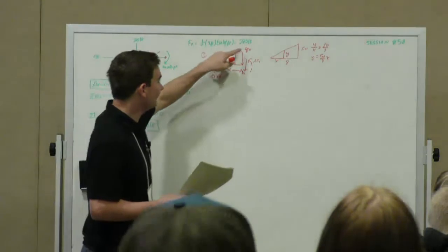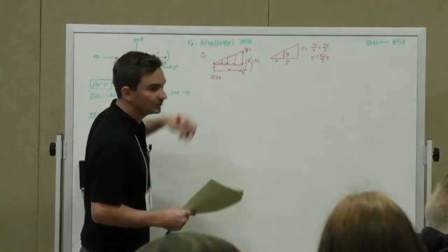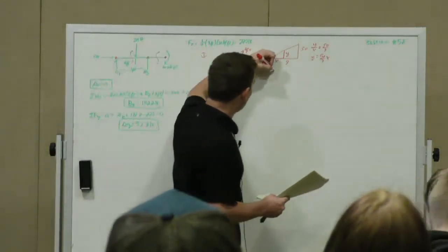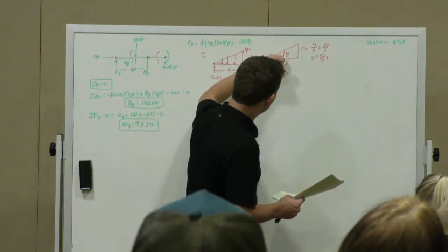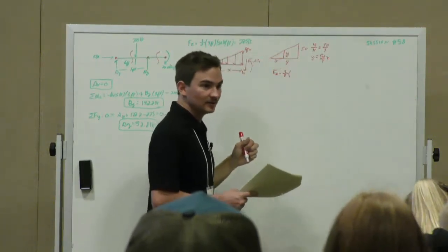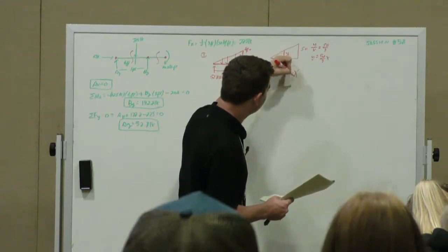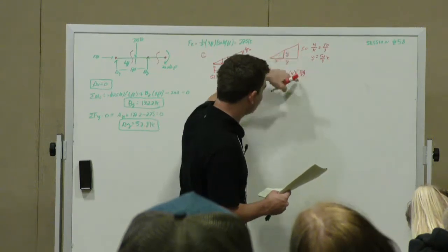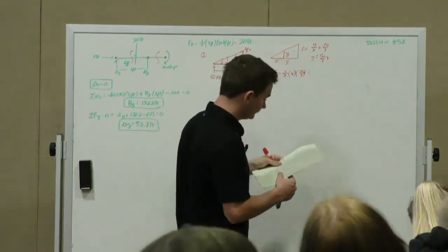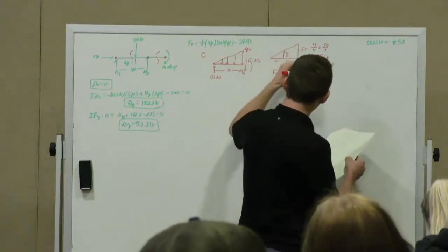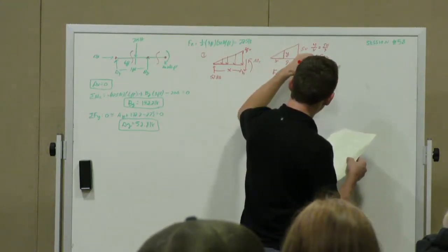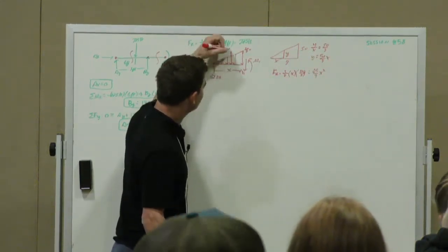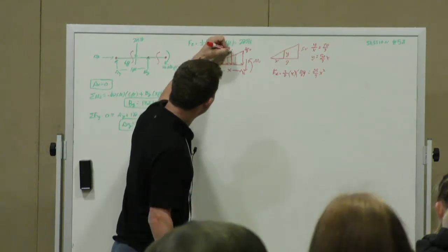All right, so now we have this height. So now how do we simplify this distributed load into just a single equivalent force? So now we could use 1/2 base times height. So the FR is equal to 1/2. And what's your base? X. Very good. Now what's your height? 50 over 9, and that's times x. So that will simplify to 25 over 9 x squared. So now we have one resultant force as opposed to that distributed load, 25 over 9 x squared.